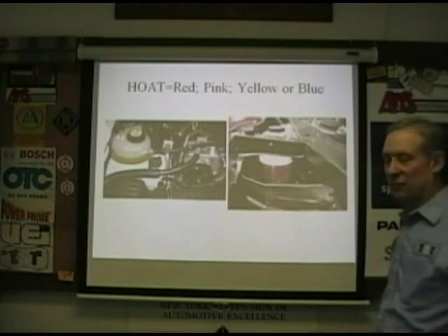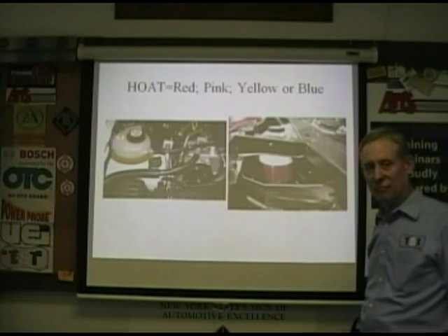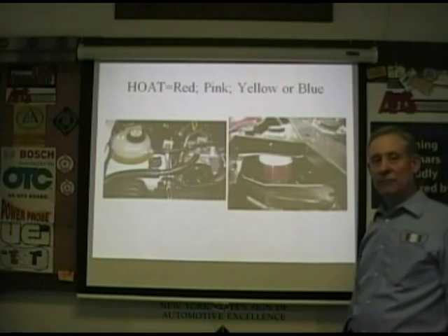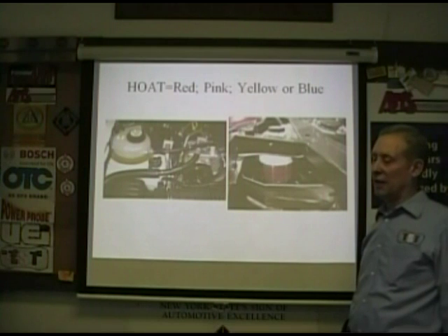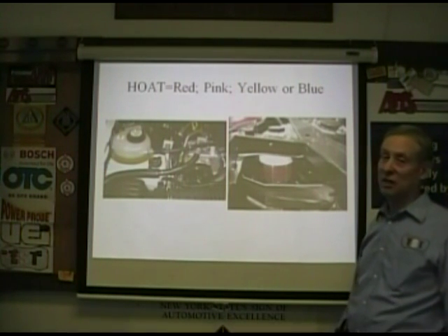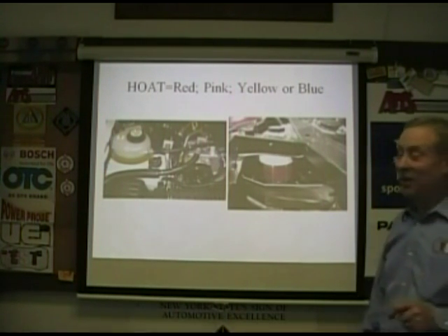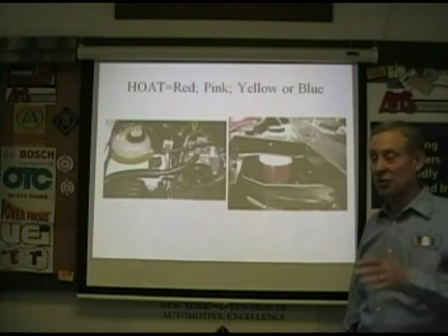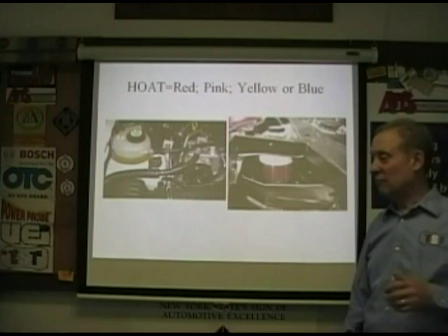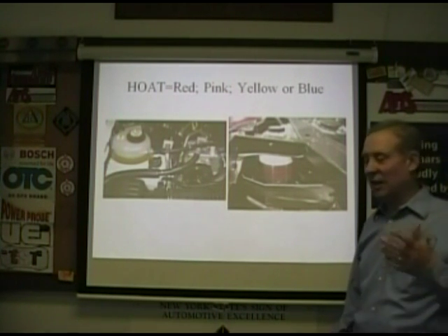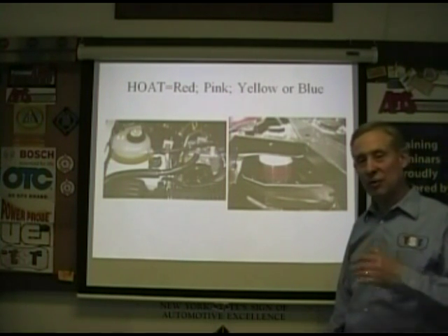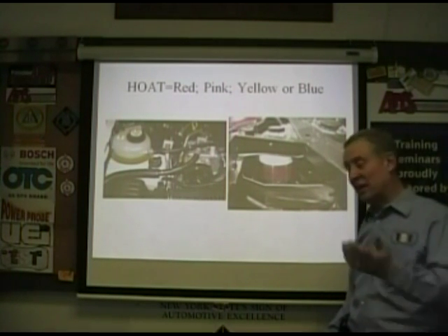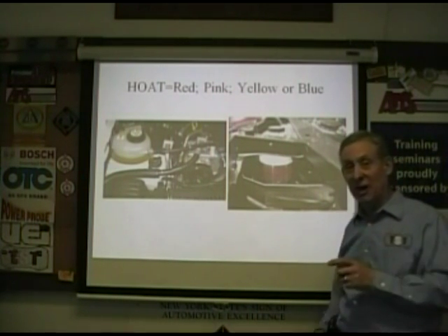And how about the guys that put additive color in when they're using the antifreeze by cleaning it up and recycling? That's the other issue, and that's part of why I say if you don't know what's in there, I'm going to say it again. If you don't know what's in there, you have to flush it out and make sure the right stuff is in there, because there are shops who are selling remanufactured coolant. They have a machine that cleans it out, strips all the dye out, supposedly neutralizes, sets it to the right pH, puts an additive package back in, and then puts a dye in.